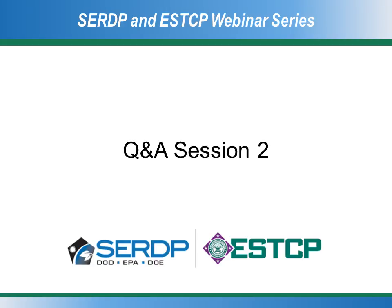The other thing is for a borehole survey, sometimes people want to come in and do a survey after the fact, after the boreholes have already been put in place, and an ERT survey maybe just wasn't considered at the onset of putting in these boreholes. So once that aspect ratio gets above 0.75 or much above it, you're really limiting your capability to image in between those borehole locations. If that aspect ratio was quite large, it might be better almost to do a single borehole survey rather than try and do some type of cross borehole survey.